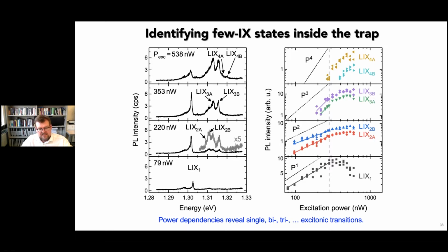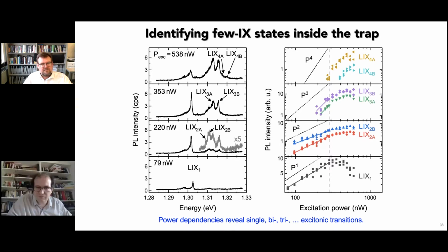If I come to more specific questions now, a lot of these crystals have been grown, for example, with chemical vapor deposition. And you can show thermodynamically that at the typical growth temperatures, there's a large density of chalcogen vacancies in these crystals. Just because of the growth conditions, the temperature, and the formation energy of the vacancies, you form lots of vacancies.